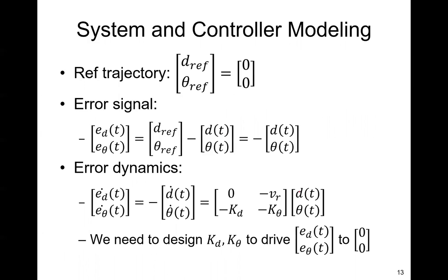And then we get the error signal. That's the difference between the reference desired system state and the actual system state, and then we plug in the controller as the P controller, no I or D terms, we get the closed loop dynamics.